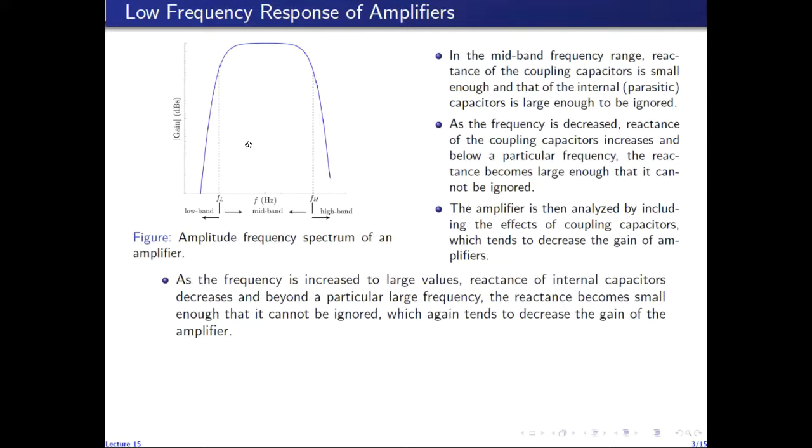So on the lower side, we only take into account the effects of coupling capacitors, because as we decrease the frequency, the capacitive reactance increases, so the approximation that the internal capacitors are open circuit becomes even better. Similarly, at the high frequency, when the capacitive reactance decreases, the approximation that the capacitive reactance of coupling capacitors is almost zero becomes even better at high frequency.